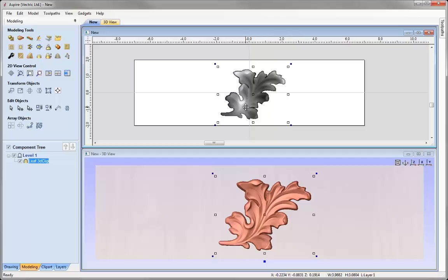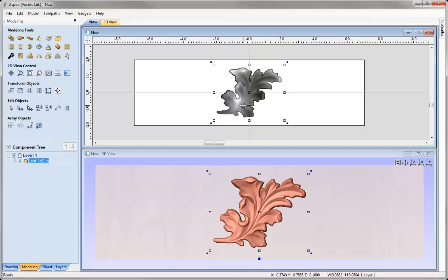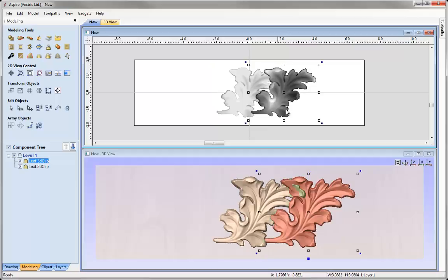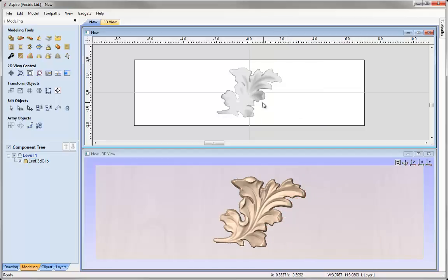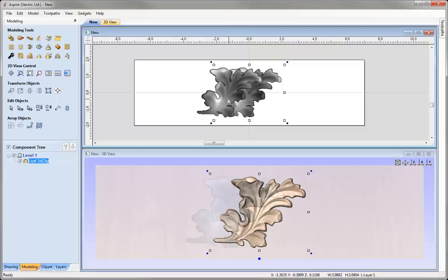The idea is that if we just hit F9 to center that, and I hold Shift and Control down, we're going to make copies of this so that it overlaps and repeats. So that if we swap that around there, we'll get this kind of an effect. What I'd like to do though is make sure the way I lay this out is nice and symmetrical. So rather than just drag and approximate it, I'm going to select this object, click it again. Remember we centered it, so F9 on the keyboard. I'm going to hold Shift down and just drag it over here.